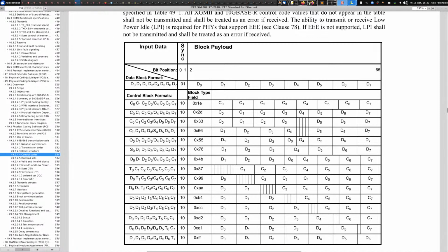Right. So I've talked about a couple different kinds of line codes and a little bit how they're used in PCI Express and Ethernet, but what do you need a line code for? Line code provides several different features. One of them is it provides framing, right? It allows you to detect the byte boundaries, and this is very important in serial links.